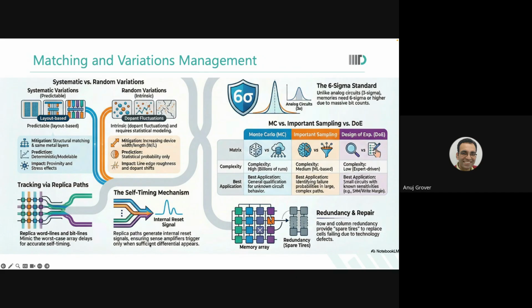The capacitance of the gate reduces. As the capacitance of the gate reduces, the control over the channel reduces. You need to apply a much larger voltage on the gate to get the same kind of current. I'm going to basic physics. What is a MOSFET? A MOSFET is a capacitor. You apply voltage on one side and control the channel on the other. It is all coupling. So if the capacitance is small, to get the same kind of current, you need a larger voltage there. What happens?